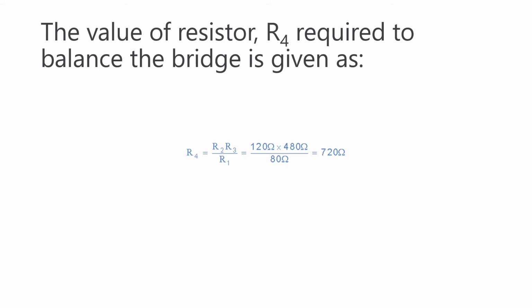The general form of the AC bridge balance is Z1 Z4 = Z2 Z3. In terms of admittance, we can give it as Y1 Y4 = Y2 Y3. From this equation, we can say that the product of impedances of one pair of opposite arms must be equal to the product of impedances of the other pair of opposite arms. The impedances are complex numbers, as we know.